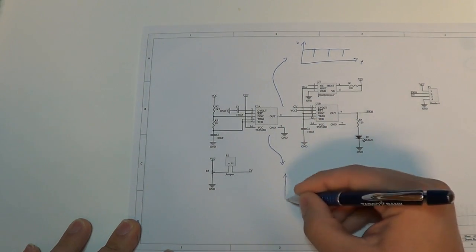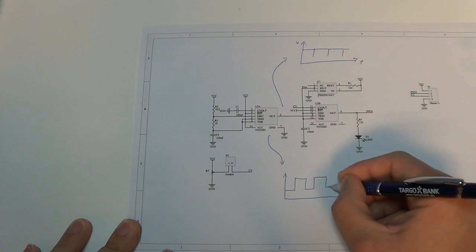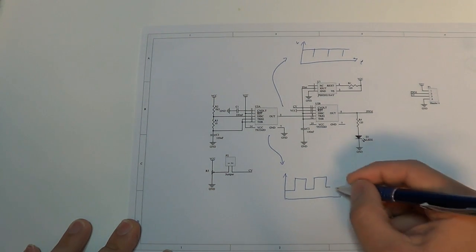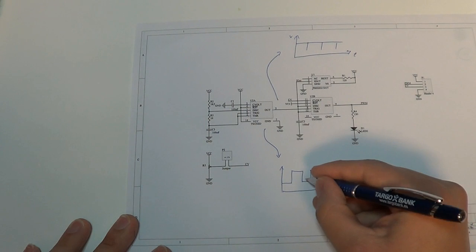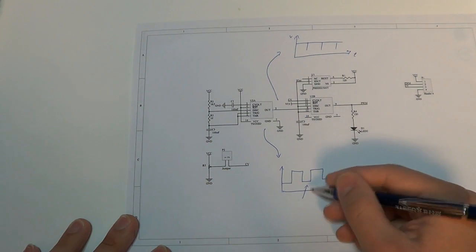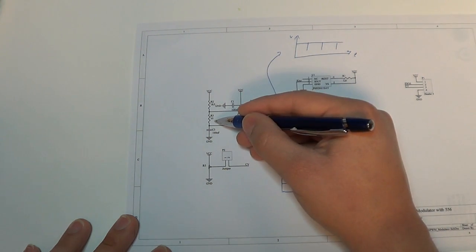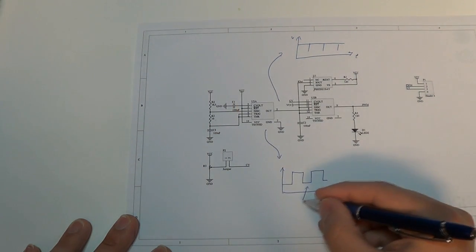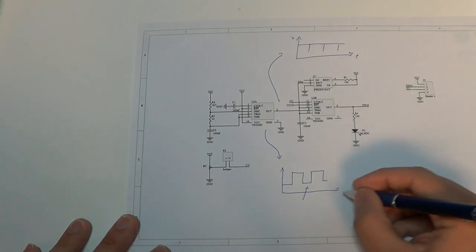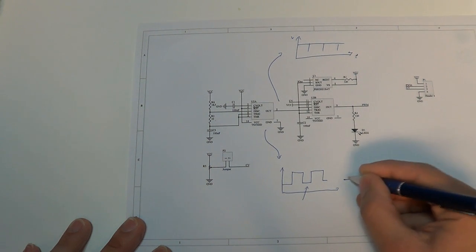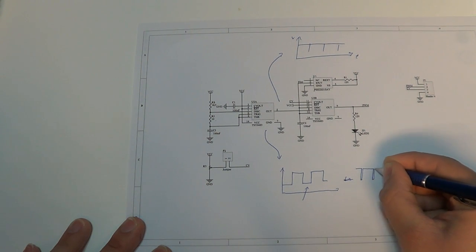And as you may know, this circuit is doing this square wave, and I will show you how it works in another video blog, but the time that this square wave is in the low state depends just on this resistor, and if you make that resistor very small in comparison with the other one, you will have a square wave whose high period is nothing.